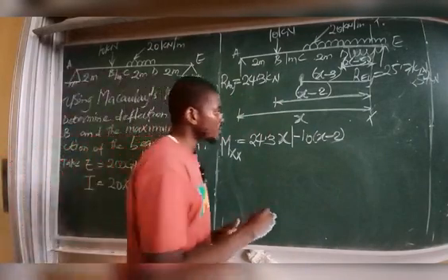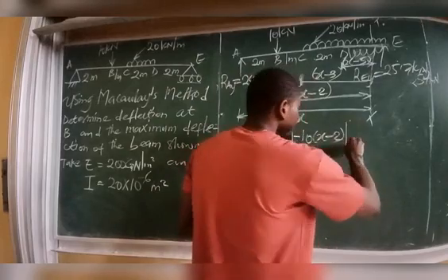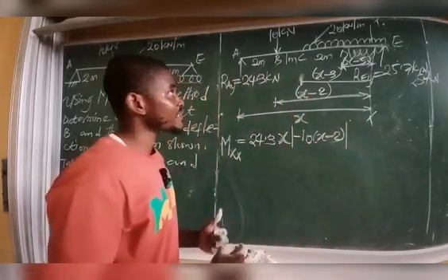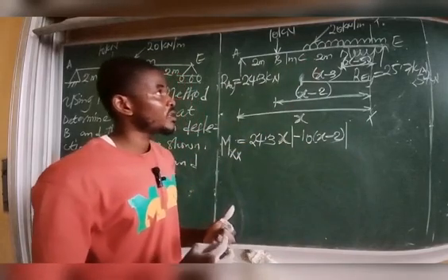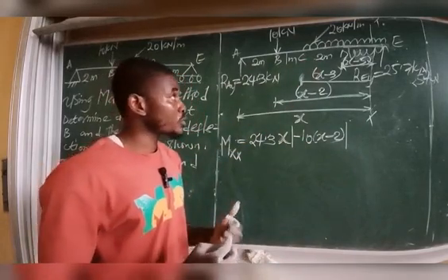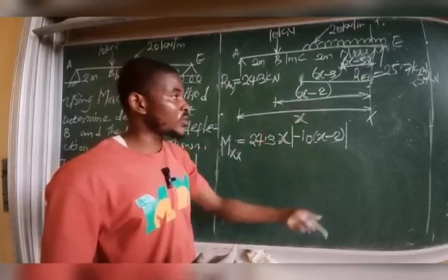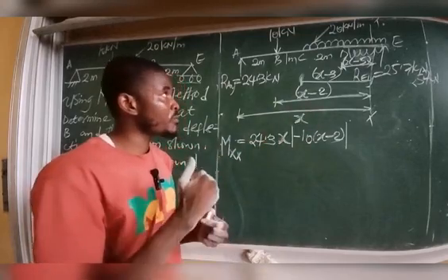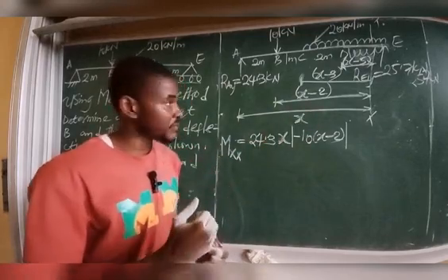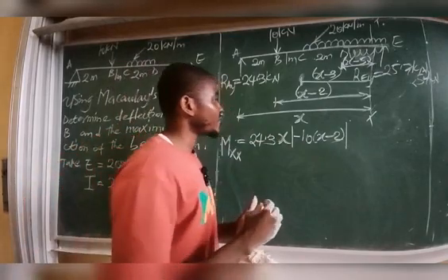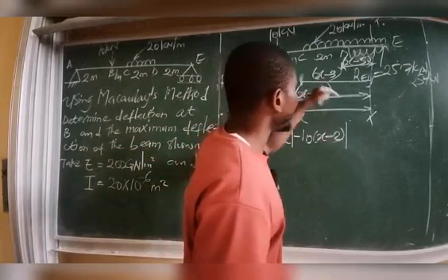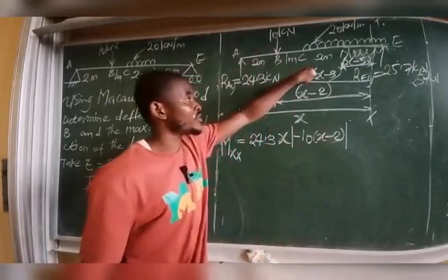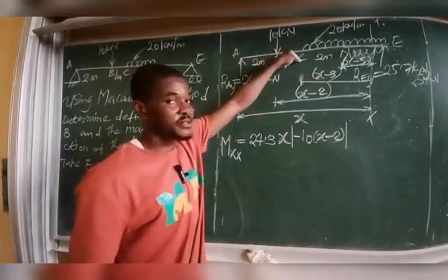After this moment as well, introduce the Macaulay bracket again. So I still bring down a bar, because I still have another load. That's the UDL between point C and the point of section. Because of this UDL, I will introduce a Macaulay bracket. So I need to take the moment of that UDL about the point of section. First things first, remember this UDL has a length of x minus 3. That becomes the length of the UDL about the point of section from point C.